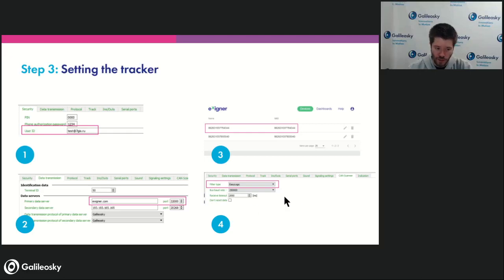Of course, it is important that since we are working with the DDD files extraction using EasyLogic algorithm, we should set CAN scanner to work with EasyLogic, which means that you will not be able to read the CAN bus in parallel.